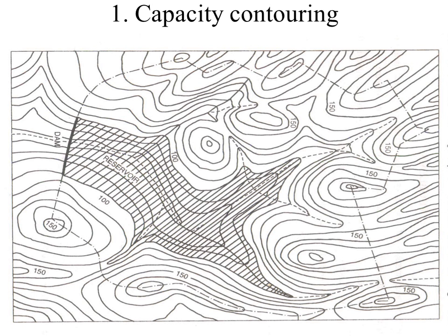Here, whenever we are choosing the dam site, we are supposed to study the location of a dam and the contour map of the adjoining area, and depending upon the direction of flow of the water at that place, we are going to select the possible location of a dam where the dam length is minimum and it is possible to store the maximum water within that particular catchment area in the upstream of the dam.